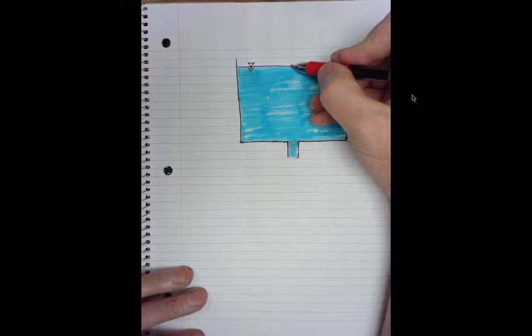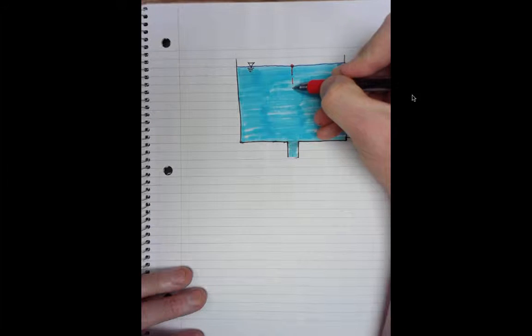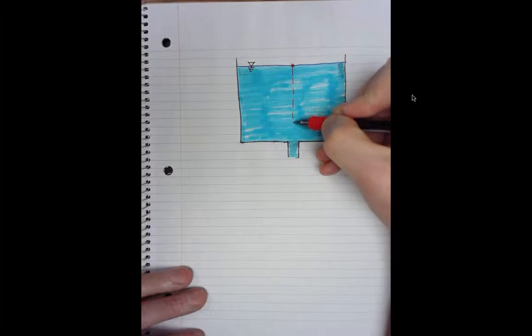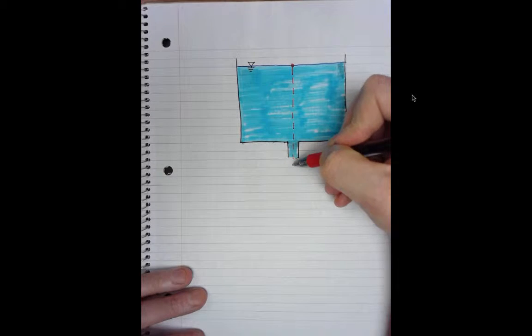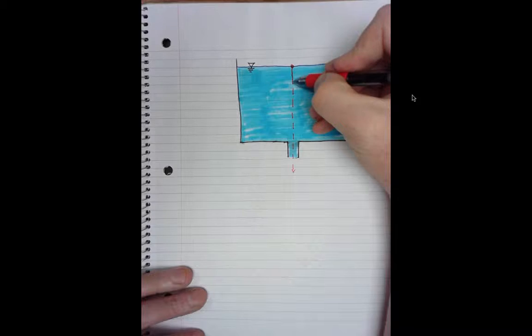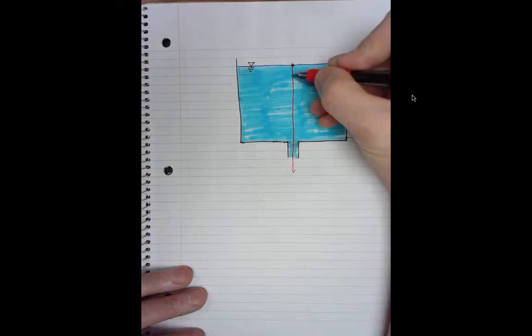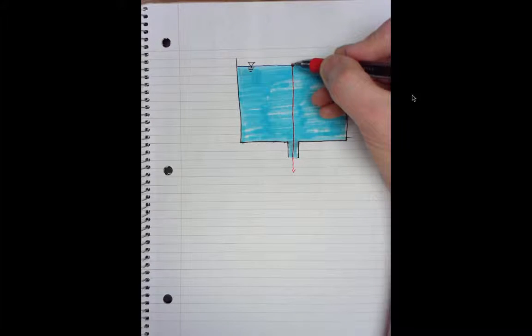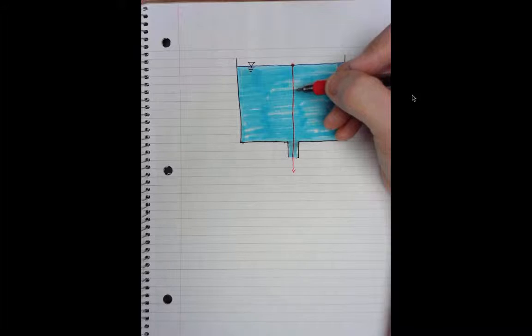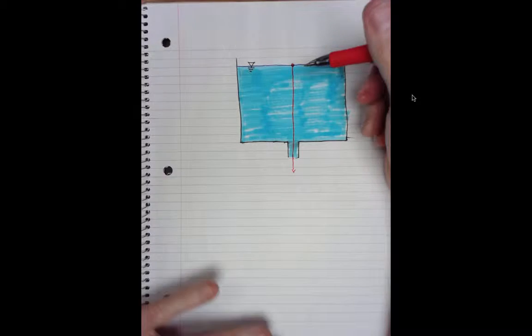Now I picked the middle on purpose because as time progresses, it's going to move this way and exit the system. It's going to follow this path. So that happens to be a path line for all particles that start up here. In addition to being a path line, it is also a streamline, and as the fluids replenish, there could be many and many of these, so it's a streak line.